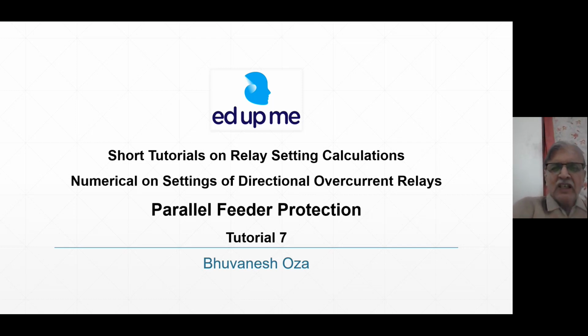In next tutorial we carried out an exercise for calculating the settings of ground overcurrent relays for a power system network in which the power transformer is there, delta-y power transformer is there. So now we come to parallel feeder, in which obviously we will have to use directional overcurrent relay, right? Because the simple overcurrent relay alone cannot be used, and you have to add the directional sense. So that is what we will be trying to do in this tutorial class.